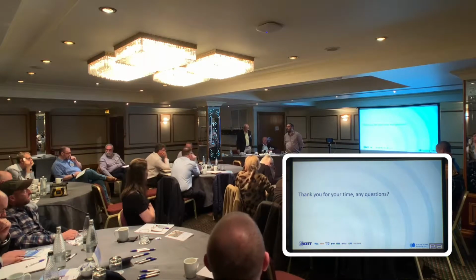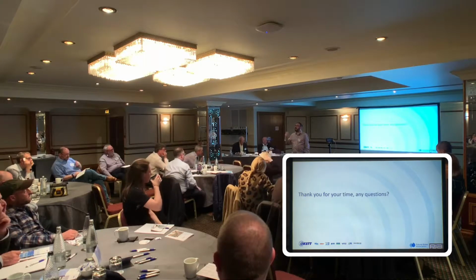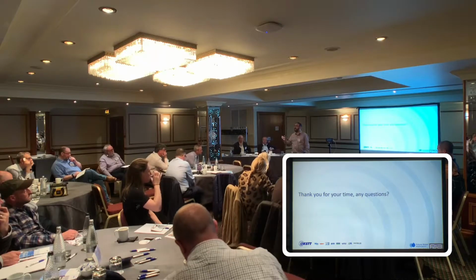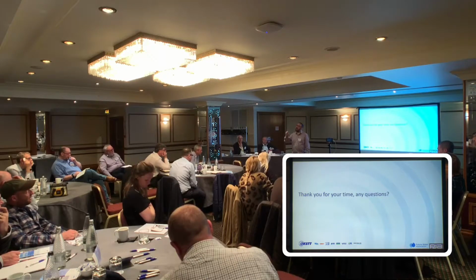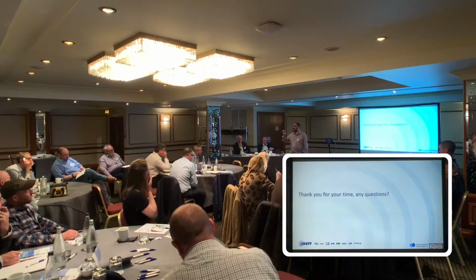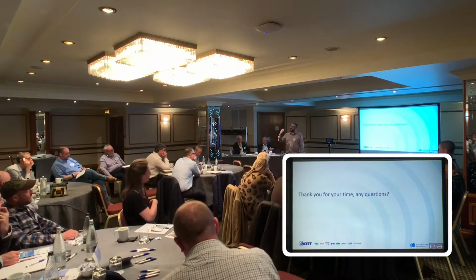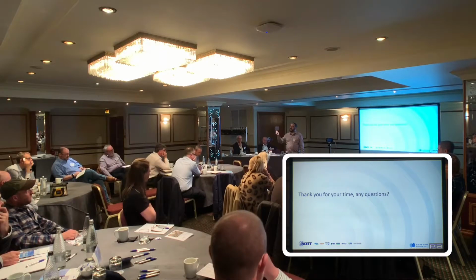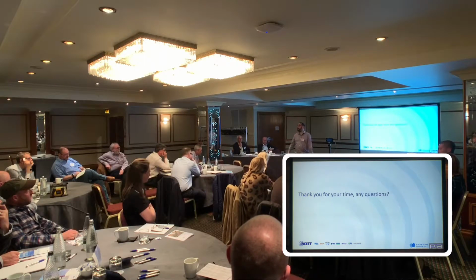The experience we've got at the moment is with the Paris Metro. Part of the brief of the Paris Metro was being able to trace the product from production to installation. So there's a simple RFID chip that goes in during manufacturing once we're producing the pipe, and that gives the segment a unique reference. That unique reference can then be used to locate it in the yard for loading sequences, and also when it's actually installed, if there was a problem with it, then you can scan it with the RFID and take that information all the way back through the production to find out which batch, when it was cast, and is there a wider problem with that product.